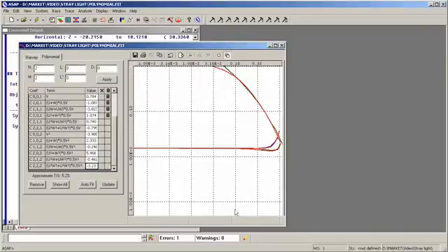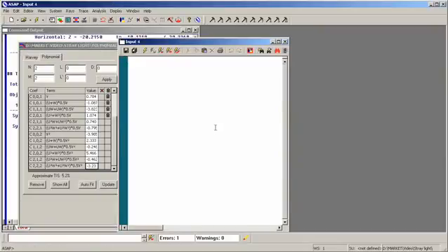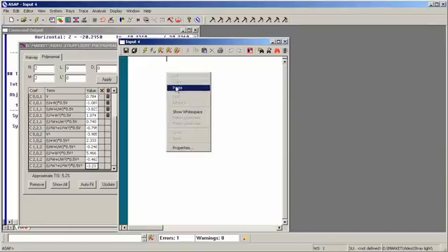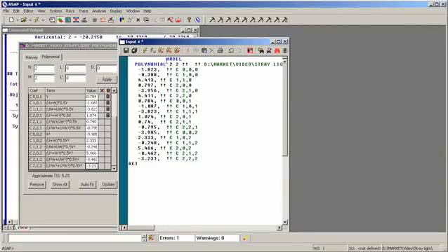Okay, we've now fit our BRDF data. These are the values of the coefficients. Entering these into ASAP could be a rather tedious process. Fortunately, we don't have to do it. We can let ASAP do it. We simply go over here and say copy this particular model into ASAP. Click. Open up an ASAP editor and paste. Here's our BRDF model, already taken care of for us.